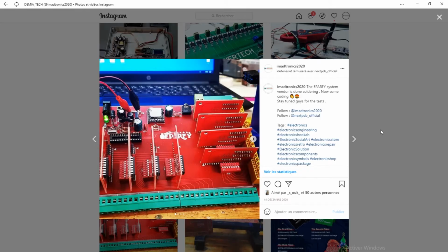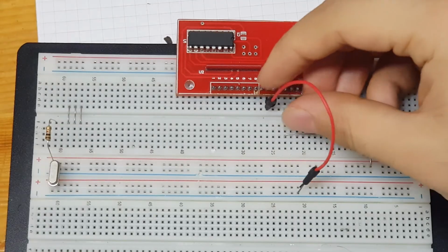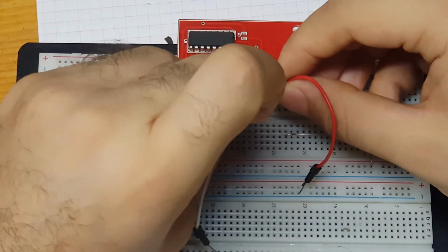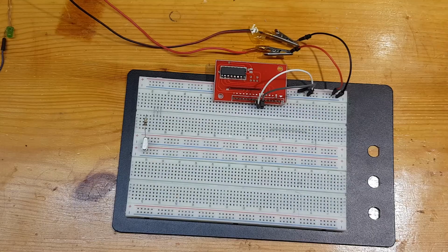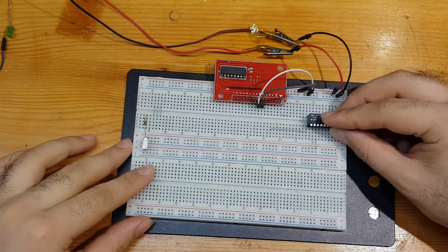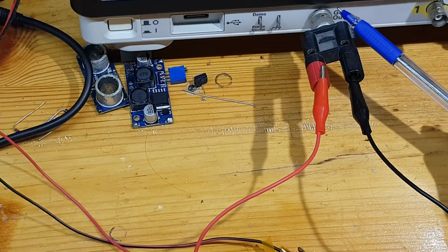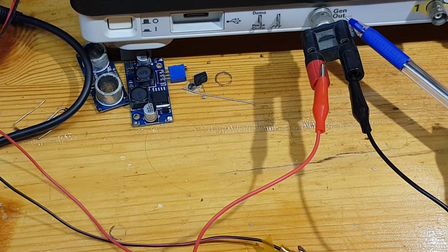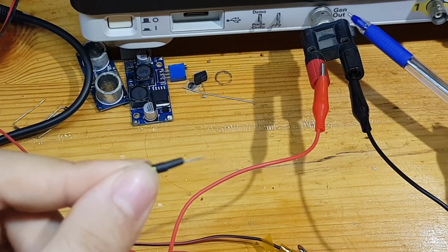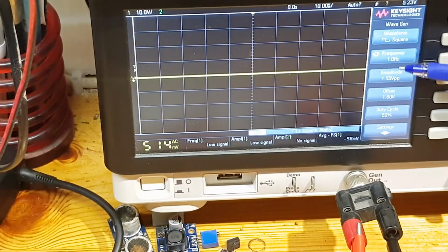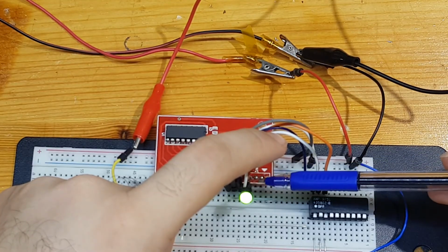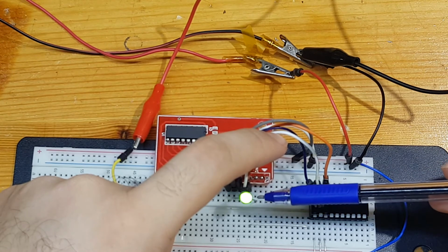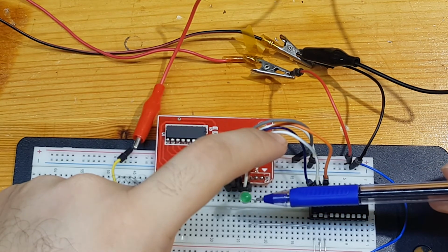For the functioning part, I hooked a wire to VCC and another wire to ground. Then I applied power to the board. Next, I've decided to add a dip switch to the address lines. I took my input right from the signal generator, so I connected a wire to it. Finally, I applied square wave signal with a frequency of 1 Hz. And after choosing the right address in my example, binary 1-1, the output got multiplexed to the input 5.